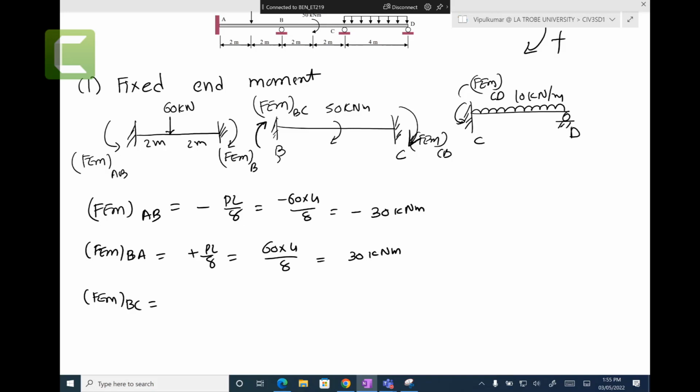Yes, one more. When we do the equilibrium equation for that section, don't we say these sections are not in equilibrium right now? That's what you said, section BC is not in equilibrium. And I agree with you, they are not in equilibrium. We purposefully make them in equilibrium. They won't be in equilibrium until we do the moment equations, not the fixed end moment.